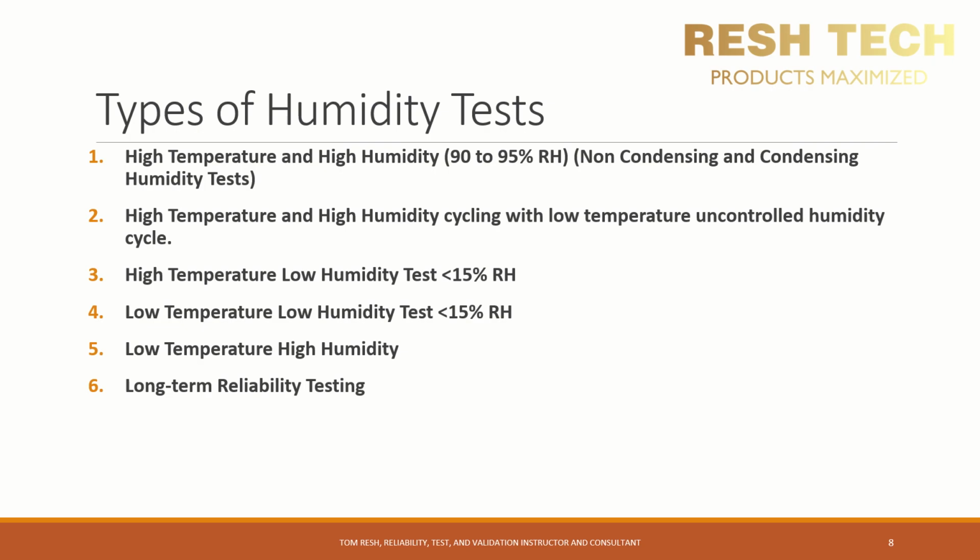A condensing humidity test is where you might need to get a little creative and put your engineering brain to good use, as the strategy here is to get the water vapors in the air to condense on your test sample. There are many different ways to pull off a condensing test, including attaching a cold plate to your test sample or building a chamber within a humidity test chamber. High temperature and high humidity tests are great for assessing corrosion effects on metallic materials, adhesion, and performance of adhesives against high temperature, high humidity environments, and even the impact of high temperature and high humidity on coatings.